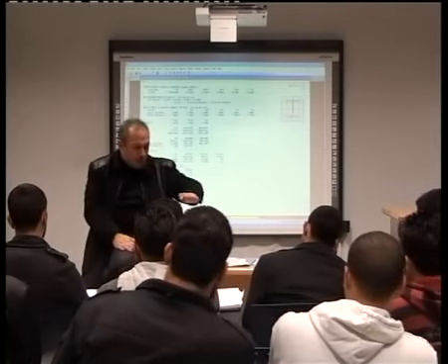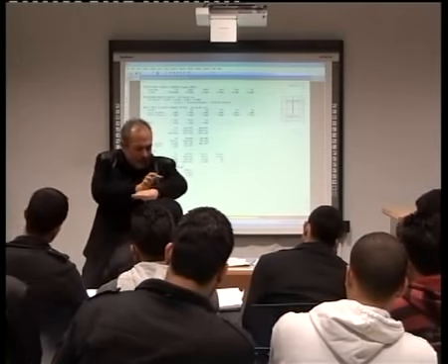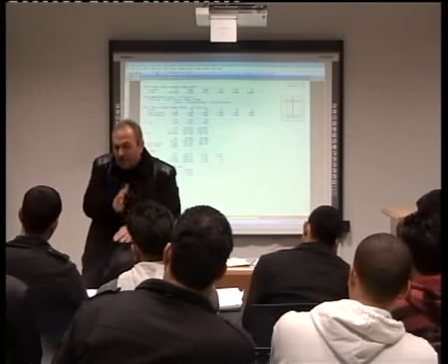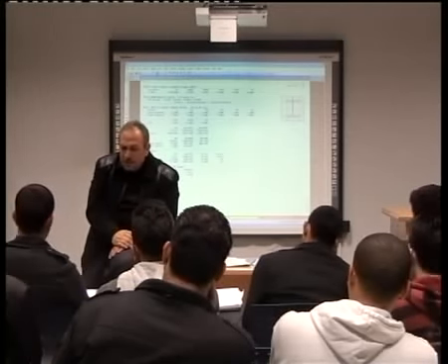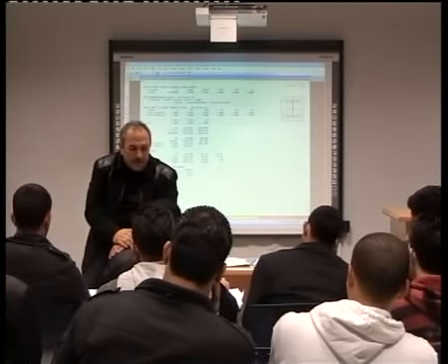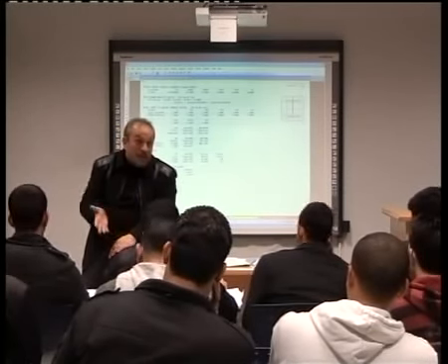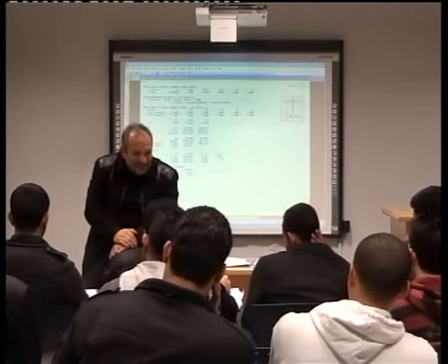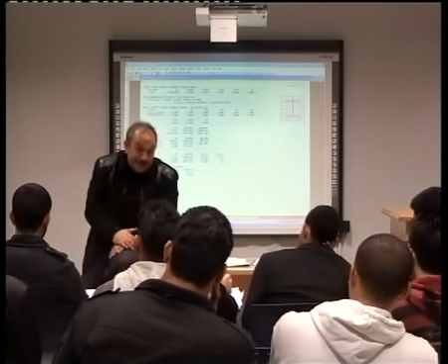When we taught you cantilevers, we said that the depth in beams is L divided by 8. In cantilever retaining walls, by preliminary design, we told you it is L divided by 7 instead of L divided by 8. Now, when we say 5 meter divided by 10, it is 50. Divided by 8, it is 60 and more.